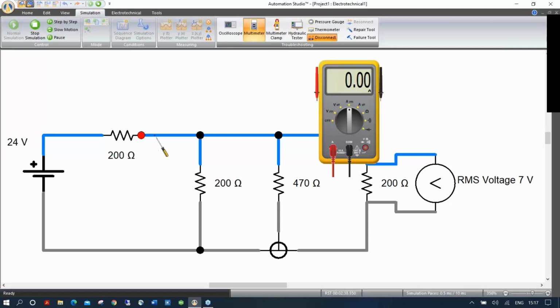Now you see I cannot disconnect this because there's too many wires here and I don't know which wire goes where, okay? So this is why, let me show you what happens when you use the splice. If I come here, click here, click there, right away it works because there's only one wire, okay? So when you make connections, I recommend to use the splice because you make sure you only have one wire at each location.